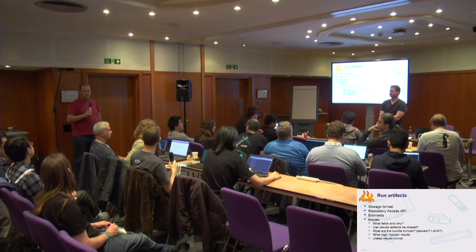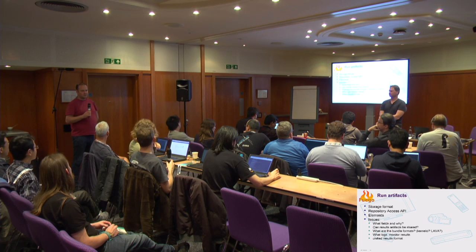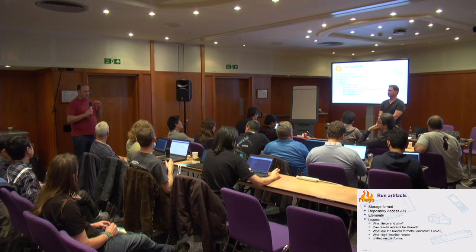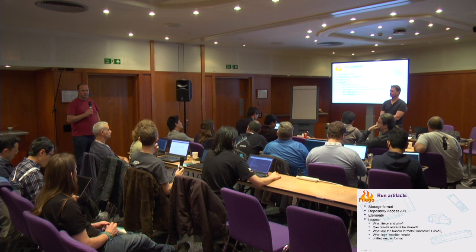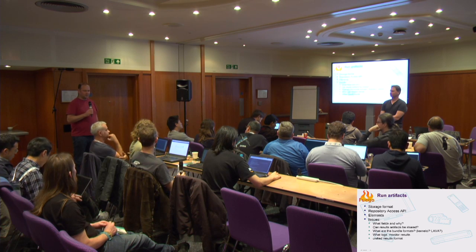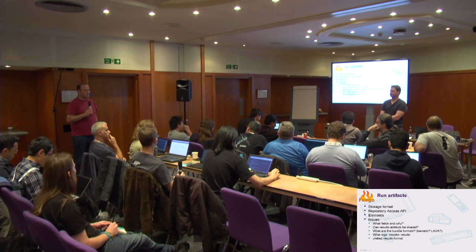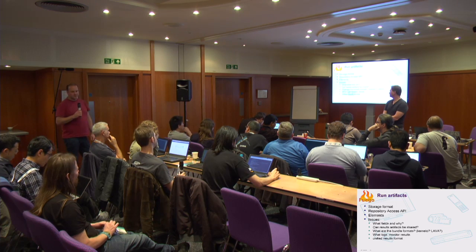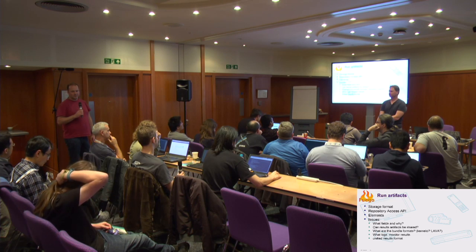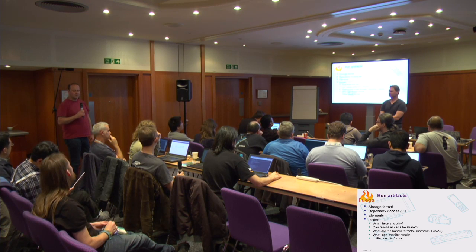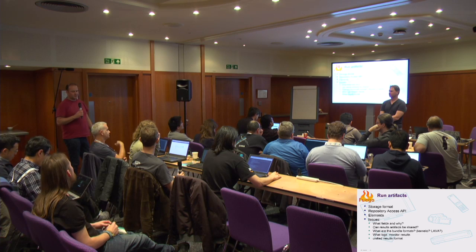Yeah, and you do also want reproduction instructions at different levels ideally. You want to be able to say, here is exactly how to flash this particular binary image that I ran on the target, and things like that, but you also want to be able to say, I built this and you can run it on your other target, which probably can actually reproduce the bug if it's a generic enough bug, without having your reproduction instructions tied to, I have this board which is made of unobtainium.